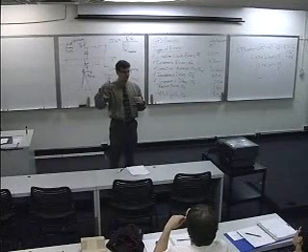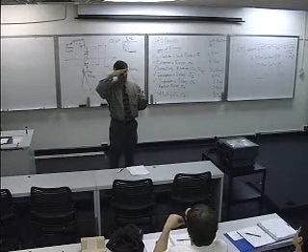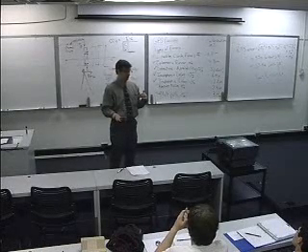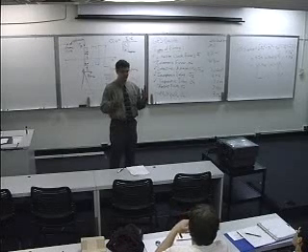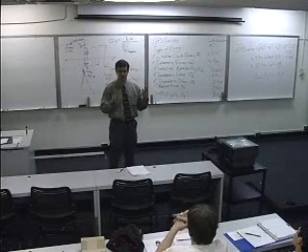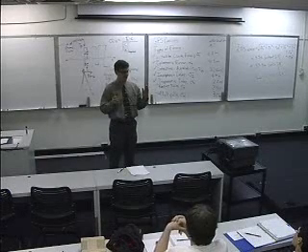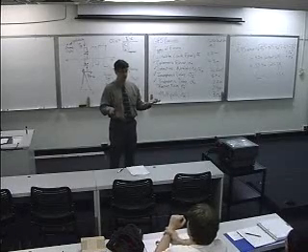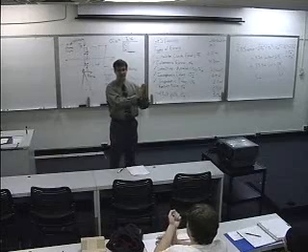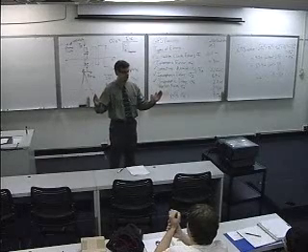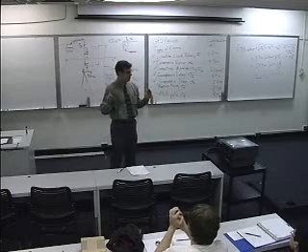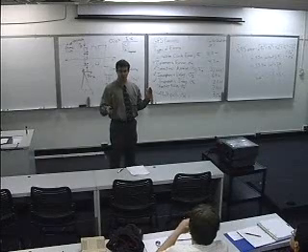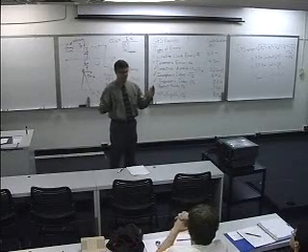And so that's why you'll see different numbers kind of bandied about. The ability to reject interference in a GPS system is based on the fact that you have 1,000 chips in the code, and you can reject about 30 dB of self-interference, or system interference, co-channel interference. But in terms of noise, you'll be able to reject 40 dB for each bit that you're decoding. And there's no law that says you have to stop at a bit for your decorrelation, right? To decode the bit, you've got to stop at a bit.